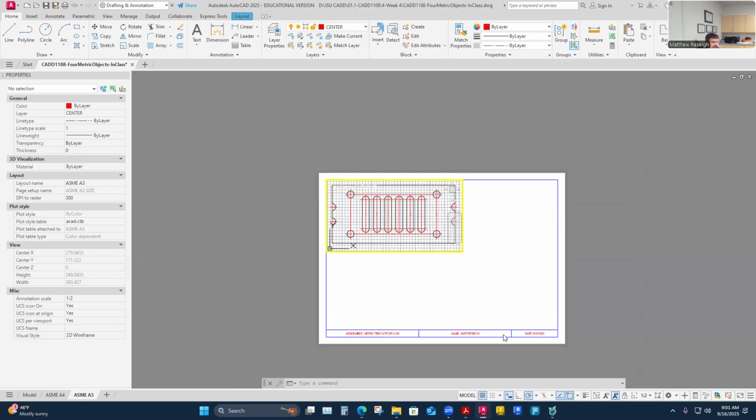So if I have an object here that wouldn't fit, even though I can make it fit by scaling it differently than the rest, then I have to make a line underneath my object and say that this is at a scale of such and such. I'd have to call that out if I'm breaking the scale that's in the title block. Normally there's a scale in a title block, and if I have multiple views, it doesn't mean they all have to be that scale. It means I have to notate the ones that would be different. And we're not even notating scale here. I'm just wanting to build that realization that this matters greatly. One to two, lock it down.